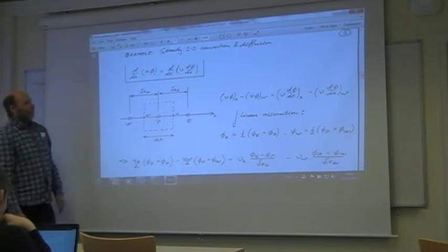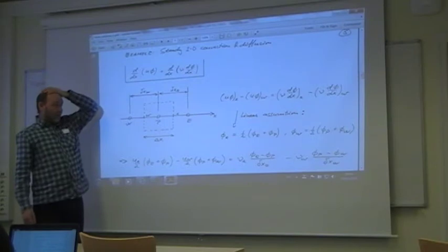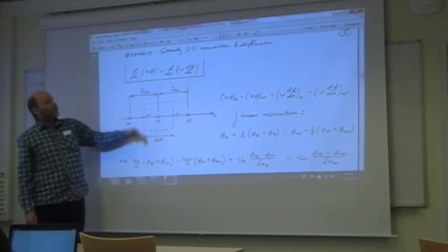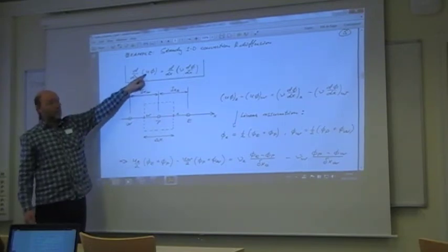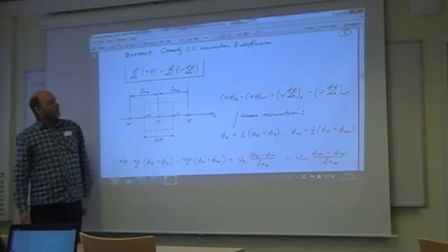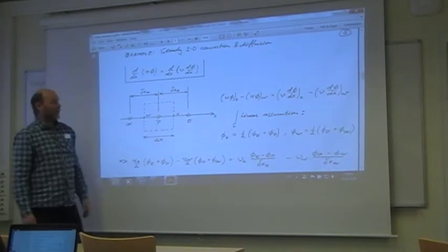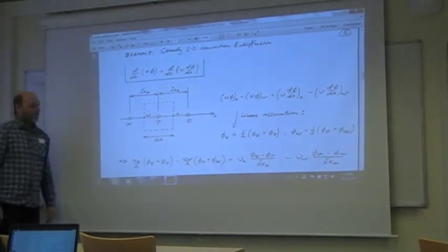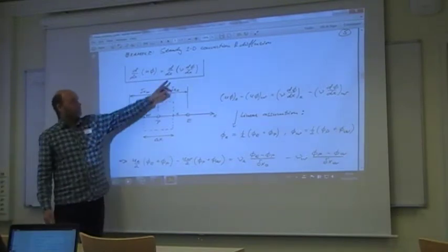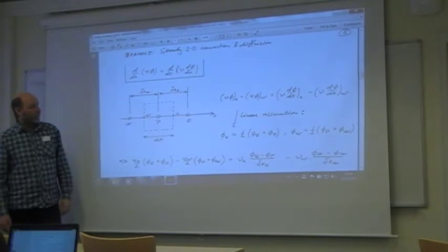And now we are talking about the same equation that we had in the example by Ferziger, the advection diffusion equation, linearized, because now we have to assume this velocity is known. And here I've used the viscosity directly. So, okay, now we are talking fluid mechanics. But of course, you could use a gamma there if you like, to have it more generic.